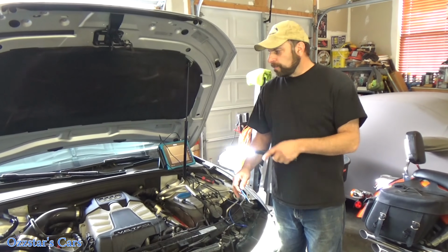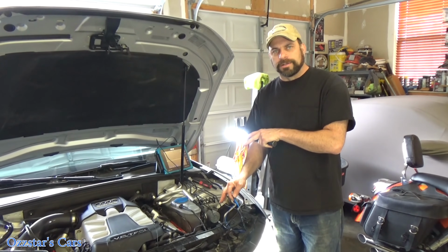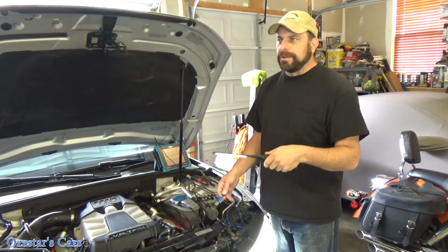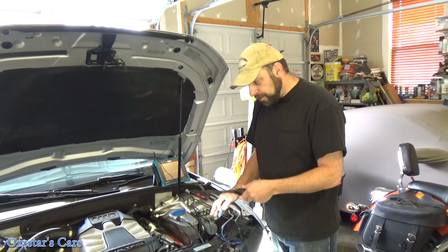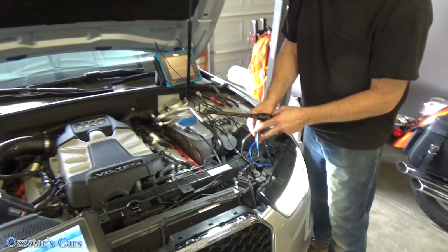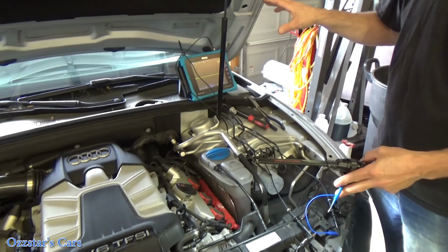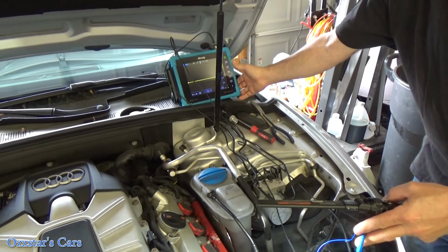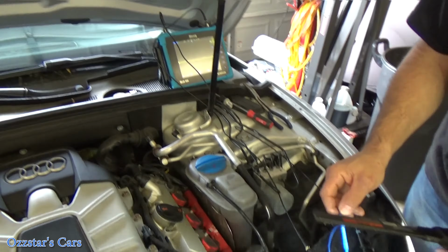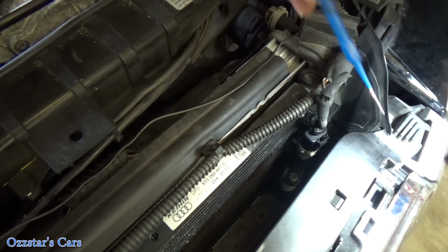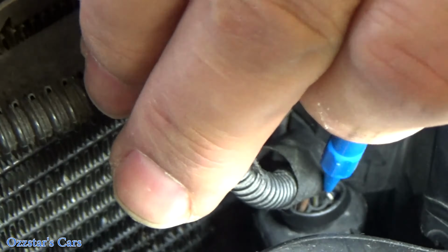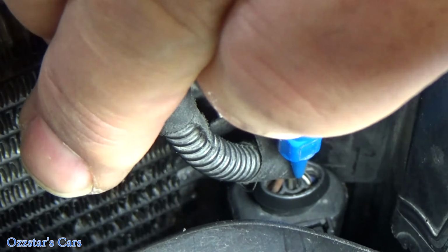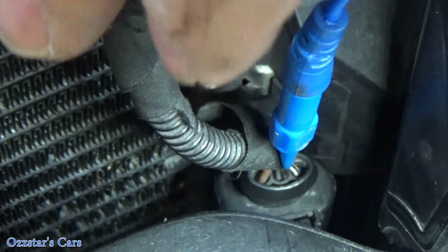All right, so I want to mention while we're doing all this, the ignition is on. So you want to definitely, in order to get the 12 volts and that ground to your connector, make sure your ignition's on, the engine's off. So now I want to show you guys how we can prove that the data link is good. Here's my oscilloscope I'm using, and I'm going to back probe. I have my back probe pin here. Now the connector is hooked up. I'm pushing down into the center, and we should be getting the signal.